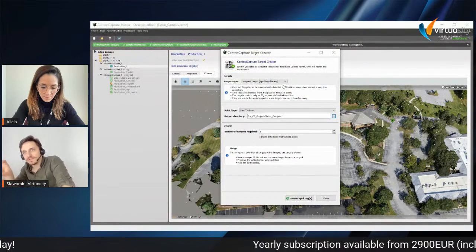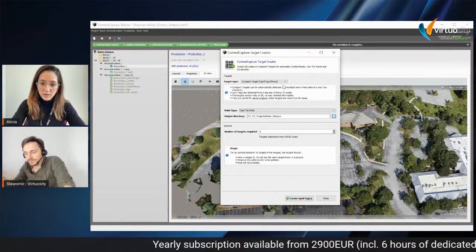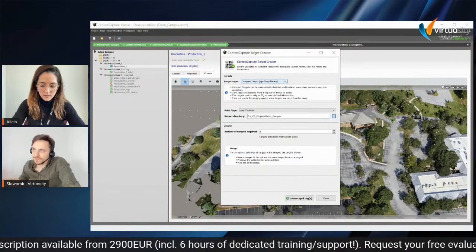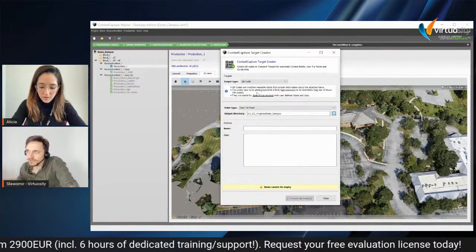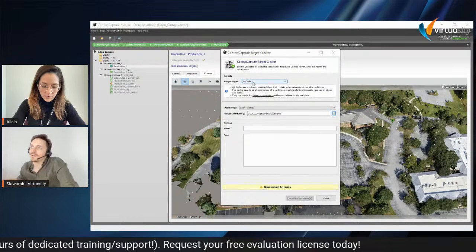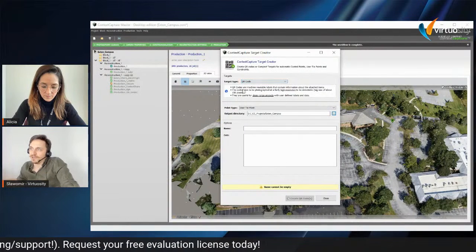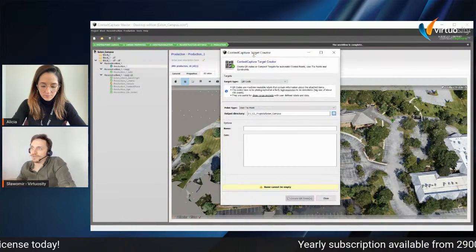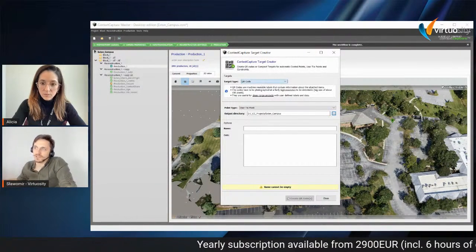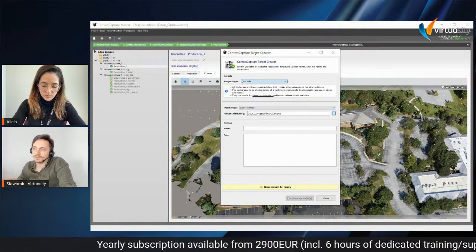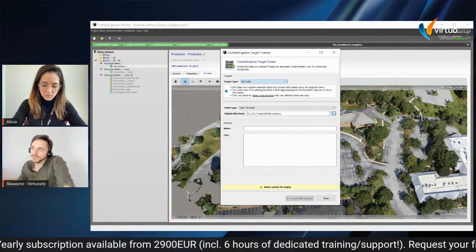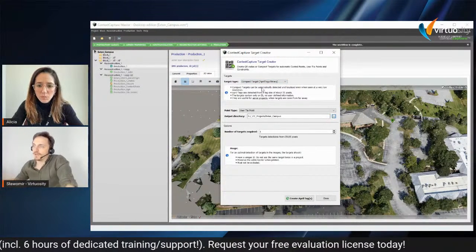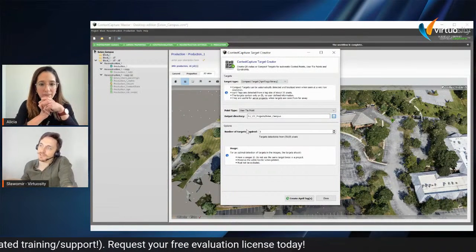April tags are much more simplified in case of the number of squares on the code, so they are much more generalized, not like the QR codes, where we need at least 150 pixels. This is a huge difference. So those are meant rather for oblique imagery, for taking close range photos of objects, maybe for archaeology, maybe for documentation of objects. But in case of aerial, we have April tags. They will just carry a number.